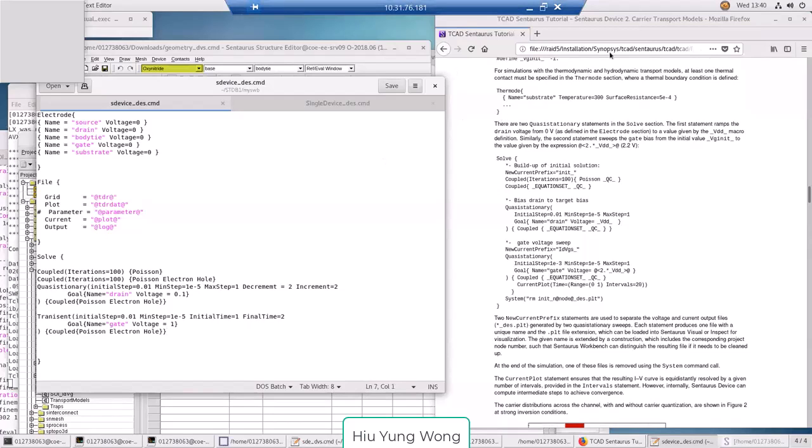For example, when I try to bias a transistor, I put 0.1 volt here. I have to ramp it from 0 to 0.1 volt, right? It cannot be 0.1 volt before. Then if you look at the drain current, you always take finite time to settle. Even this time can be very short, maybe 1 picosecond or 1 nanosecond. Still, this is the real case.